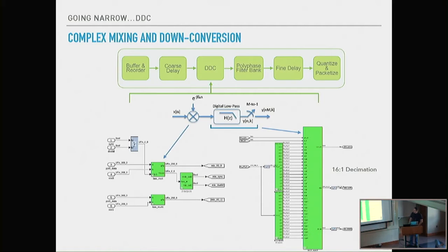So, how do we actually do this in practice? I haven't shown the logic for the actual sine and cosine lookup. You just have to take my word for it that it is part of one of our input ports there, but it's nothing more than a CASPER multiply block coming in where our two inputs are our data, which has come from our coarse delay, and our lookup values from our DDS, or our direct digital synthesizer. We then pass that through a low-pass filter, and we can then downsample.